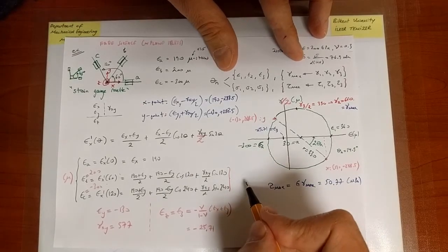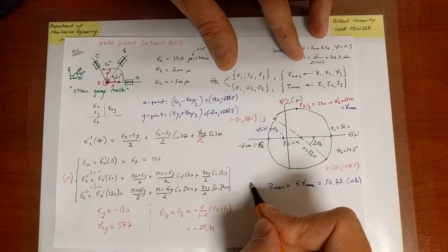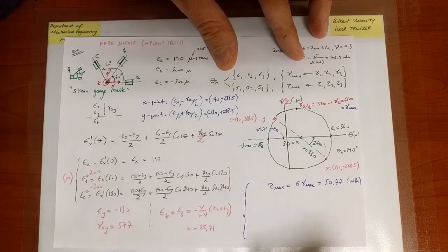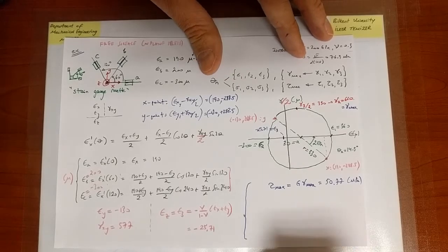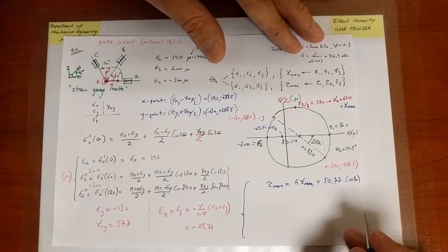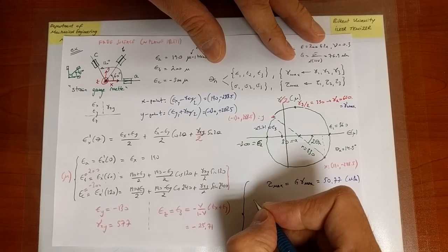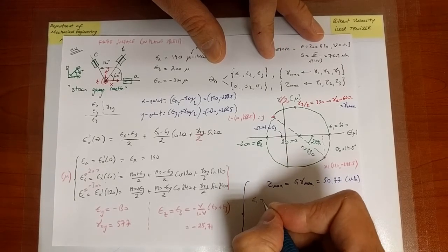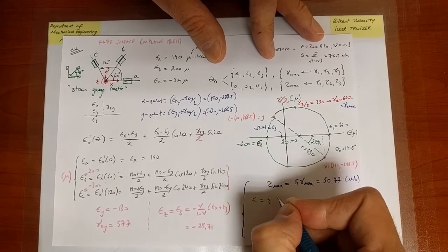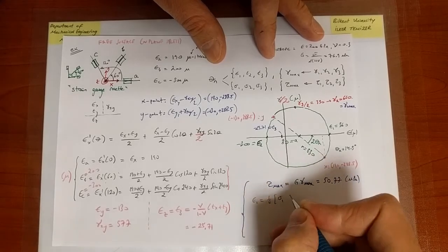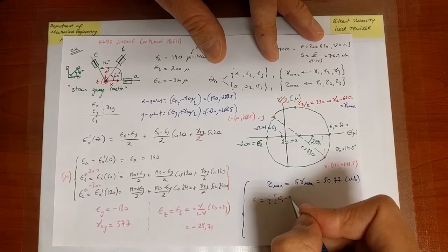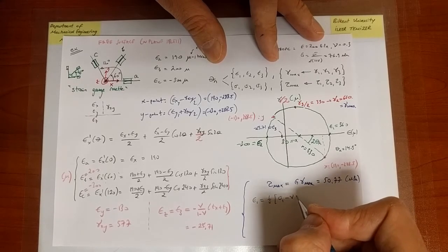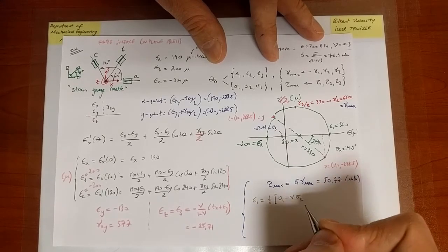Well, to calculate the principal stresses now, what I have to keep in mind is what I've said before. The relation between stress and strain holds in the same fashion for all types of choices of coordinate direction. So in particular, I can choose the principal direction, and with respect to that direction, I'm going to have the stress in the corresponding direction minus nu times the stress in the remaining directions, which is nu times sigma 2 plus sigma 3.